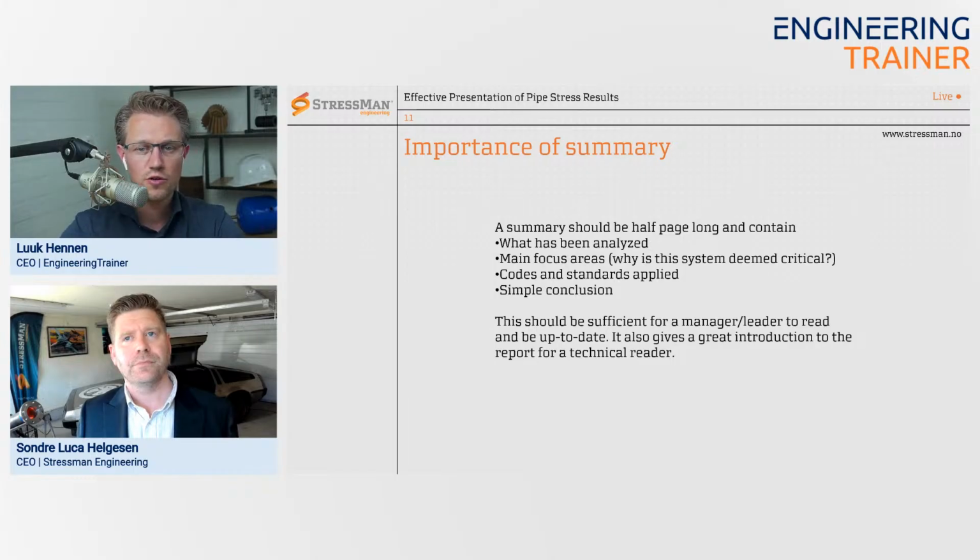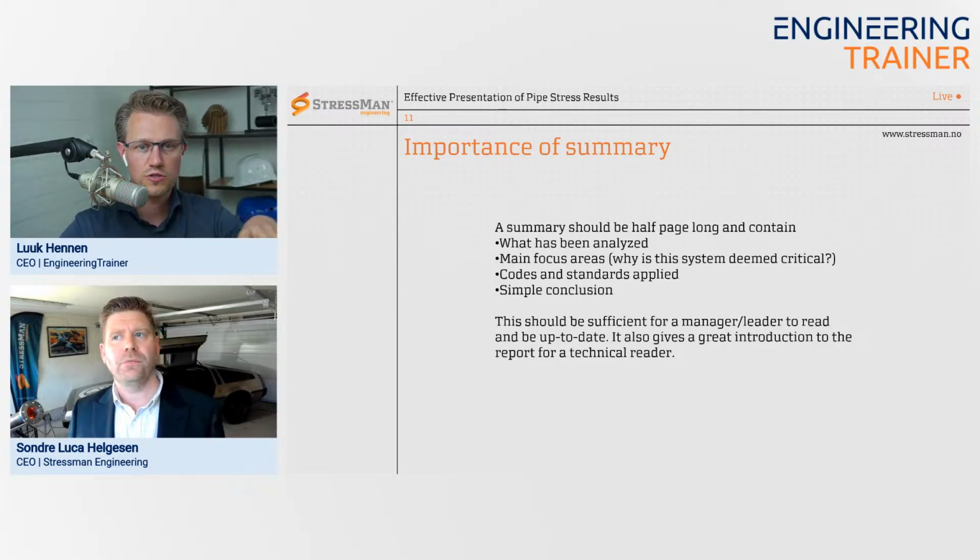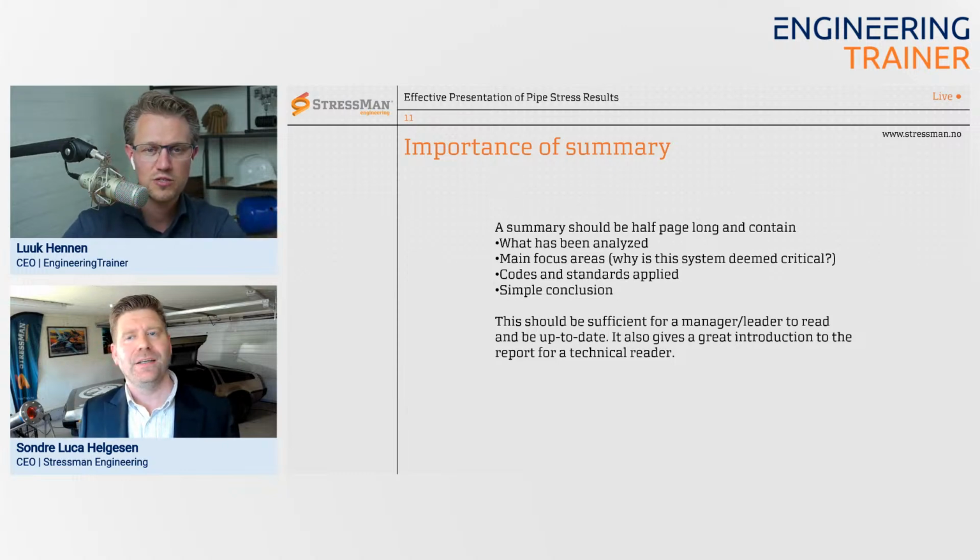Maybe the loads are just reported for the static department to discuss. Do you see that happen often, and how do you go about it, that you include the nozzle load check, like WRC or any other route, in this pipe stress report?